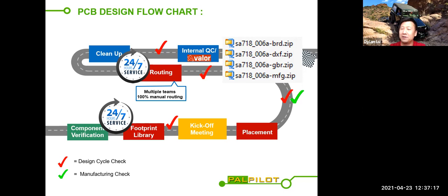Now, with good software, everything you have studied on the first go-around and all the rules you put in will be embedded with the design board file. So it doesn't matter who takes over that job, the same limitations and same rules are going to regulate that environment when you work from that PCB. But for some not-so-powerful tools, your intent from when you did the design will have to be passed on verbally or in a different documentation format to whoever is going to pick up that project. That tells you how important the tool capability is.